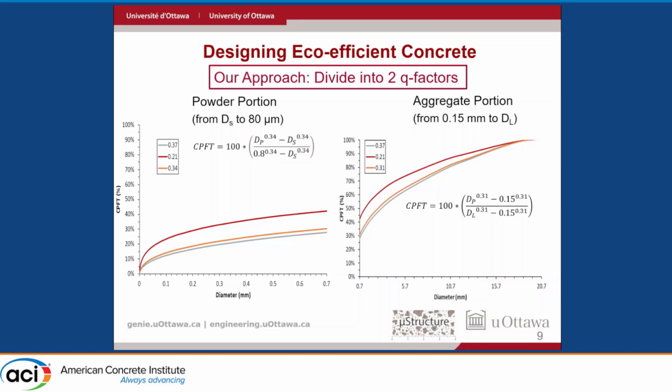Normally, what we finish by doing is to try to use something as close as possible to 0.37 in the powder phase. And why? Because then we reduce the amount of fines in the system, and then reduce cement, which is good, right? But then we need to adapt the coarse phase, meaning fine and coarse aggregate, so that we get a rheology of interest.